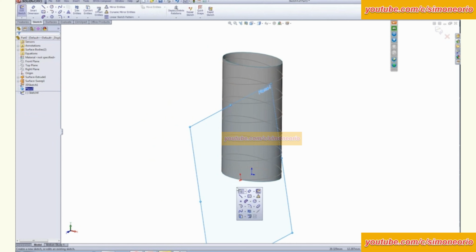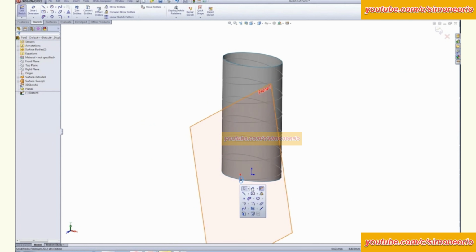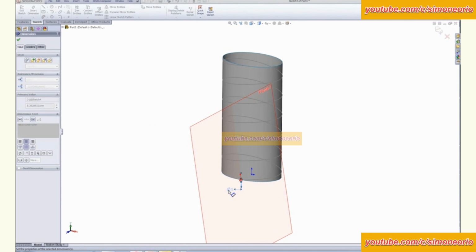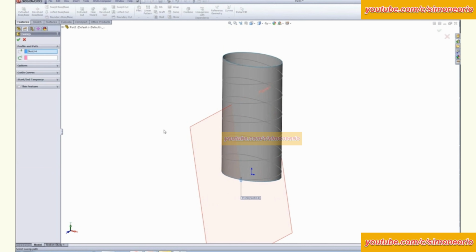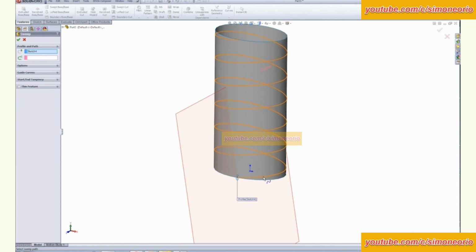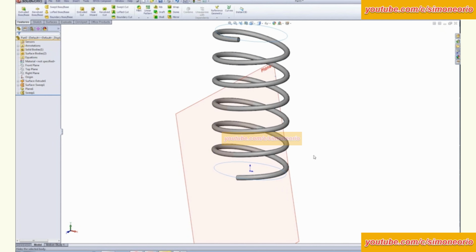On that plane, we'll grab our circle tool. Make sure that it starts there at our path. Give it a quick dimension, maybe 5 millimeters would be good. Exit our sketch, Features, do a sweep, using that sketch as our profile, and then we come in here with our 3D sketch, essentially. Better choose my path over here. And then you end up with your elliptical spring.